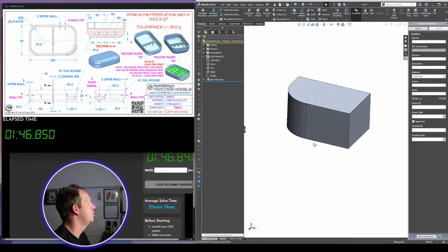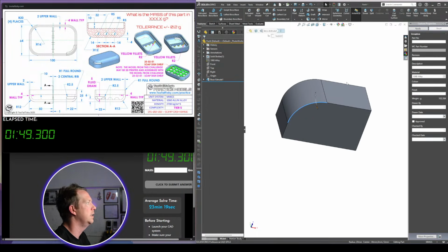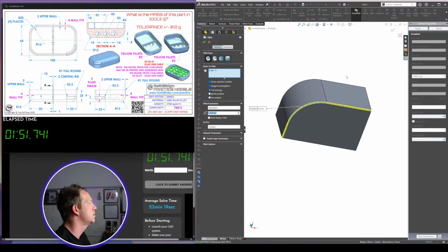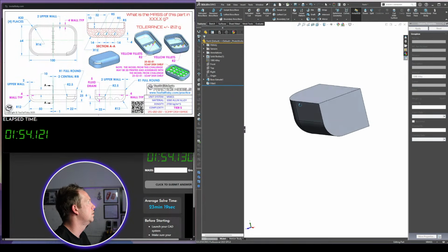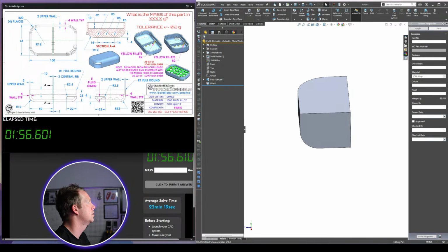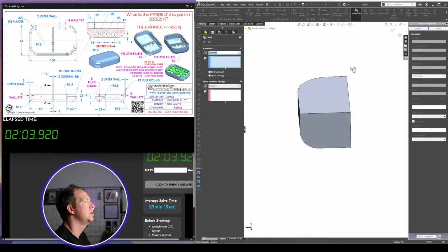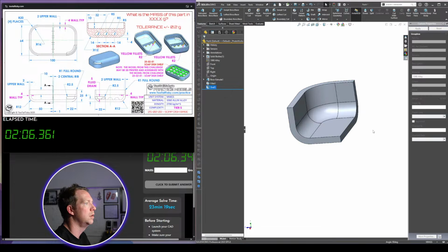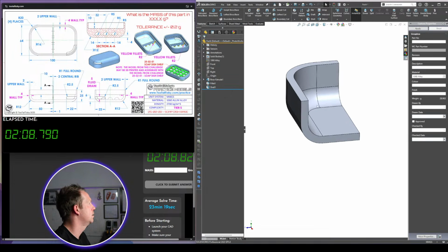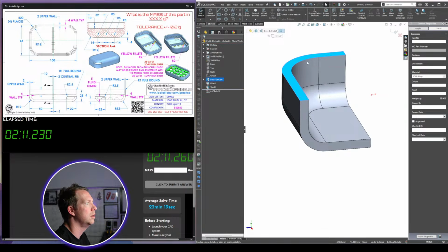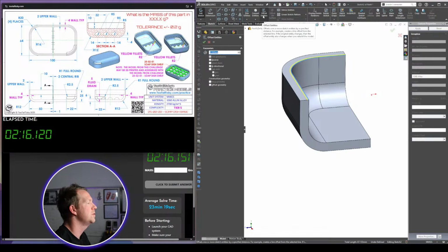Alright, so we've got the extrude up. We're also going to do the outer fillet, which we can see is 12. Now this has like a 2-stepped cut that goes around. What I'm actually going to do is go the wall thickness, which is the 4. So shell at that thickness, and then on the top edge I'm going to select this edge, offset, and offsetting it 2.